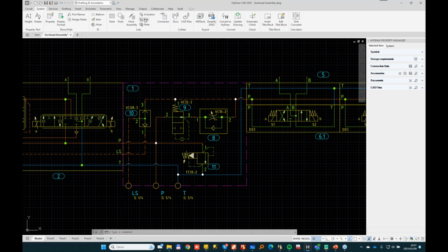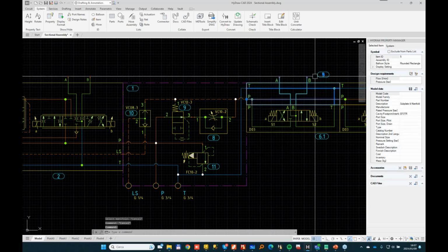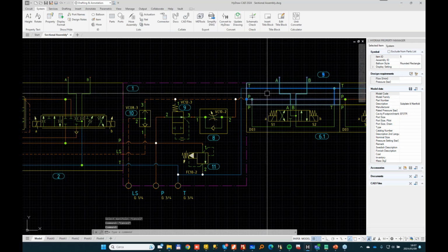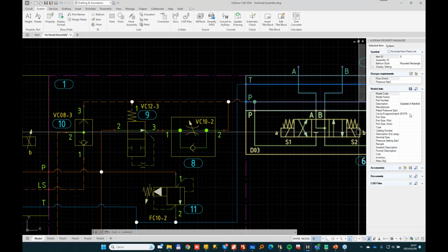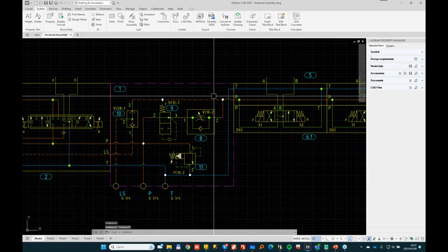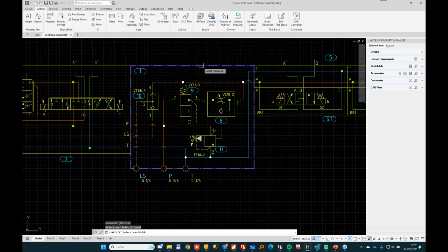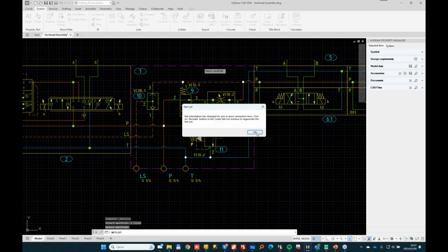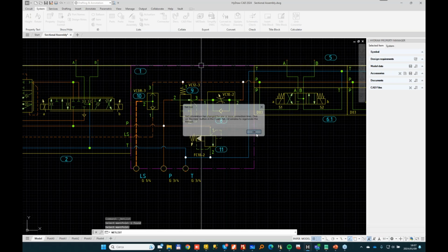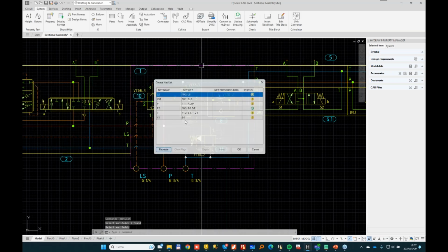We'll do a network. So we click net, select the manifold we want to design. Well, of course, the same happens for my right side. So here I have an element connected with PNT, and there is a name for the cavity footprint, EF3TR, like I showed in the library. I'll do a network command. So this command, I had already run it, so this warning says that something has changed because I have added new ports. So I just click OK and regenerate the networks.